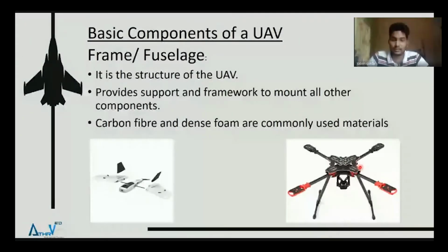It is very light and it has very high strength and a little bit of flexibility, because with too much rigidity, in case of landing or the forces acting on the aircraft, it might snap in the air, or while landing, with the momentum of the aircraft when hitting the ground, the frame must be able to give way. That is, it should be able to absorb some of the impact force.